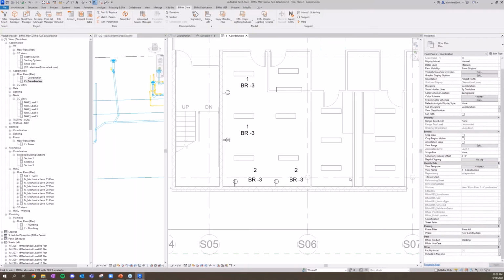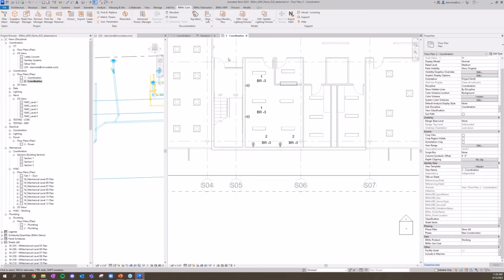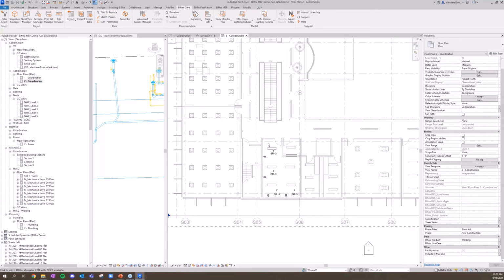Really nice stuff. We can set up one single floor, maintain that one floor as typical, and right before we issue drawings or issue a set, we can copy that through the entire building. An incredibly quick workflow. Now, we've done a whole bunch of modeling and it's probably about time to kick these things out, right? Couple ways we can do that.